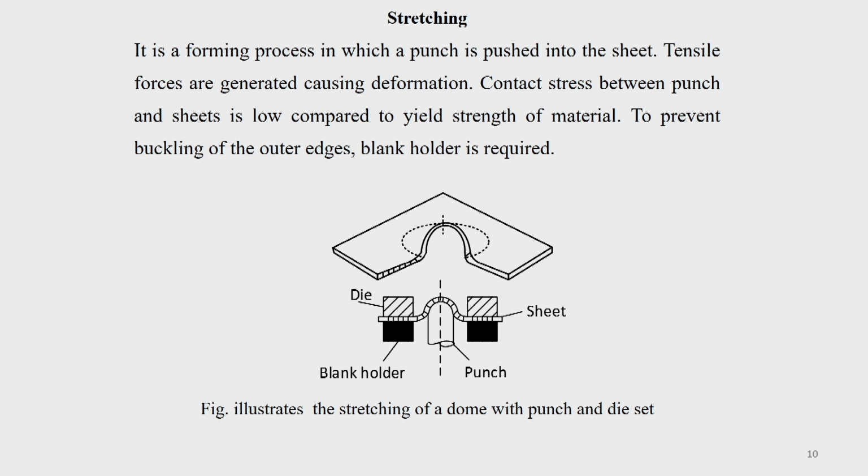Now, sometimes it is like a stretching operation, because of the tensile force. So, the sheet should be held very rigidly by means of a blank holder. Otherwise, if there is no blank holder, buckling of the outer edges will take place because it is drawn, and you may not get the shape. So, to prevent that, a blank holder is required. Then only you can have a stretching force.